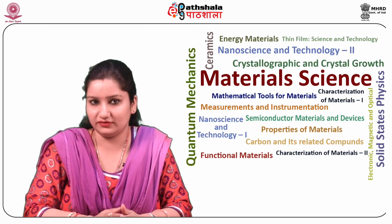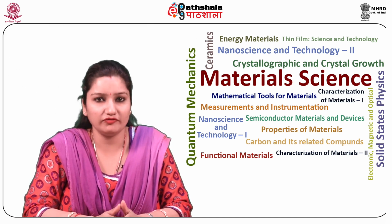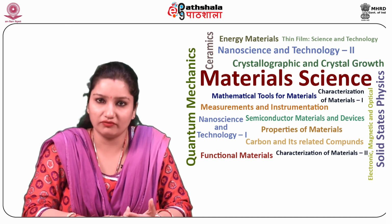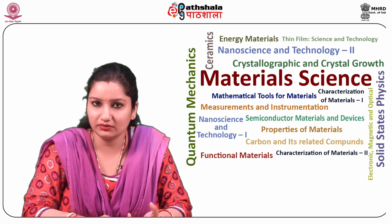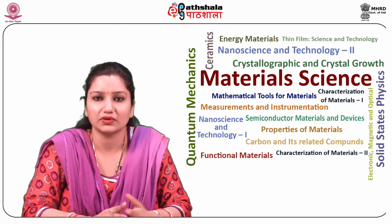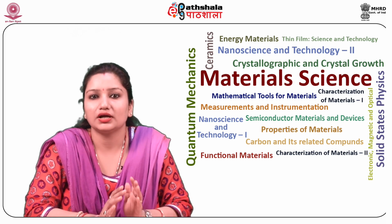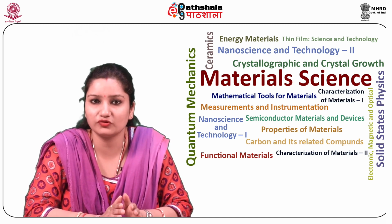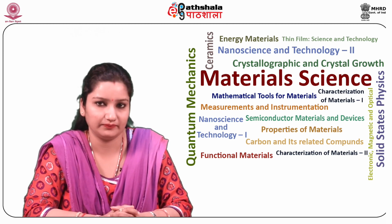Spin coating of photoresist. Resist formulation may generally consist of first, film forming resin, second, solvent, third, sensitizer or photo initiator or photoacid generator, and the fourth one is additives. The dried film coated from a solution containing the above ingredients undergoes changes when exposed to radiation of a certain wavelength or electrons or even ions.